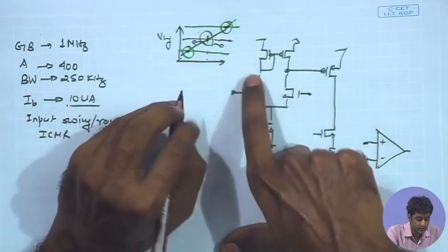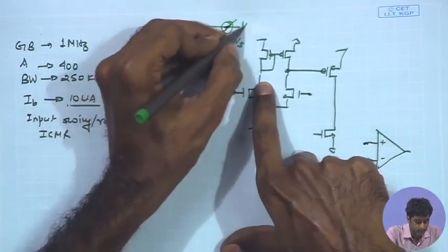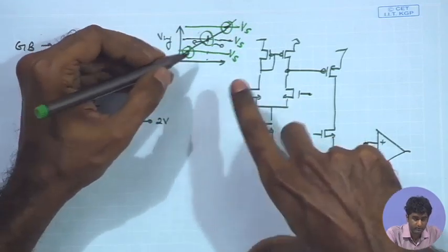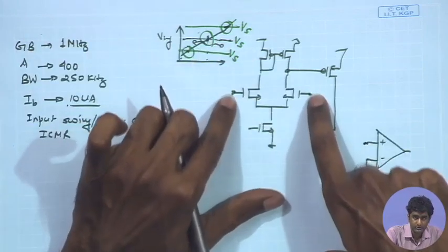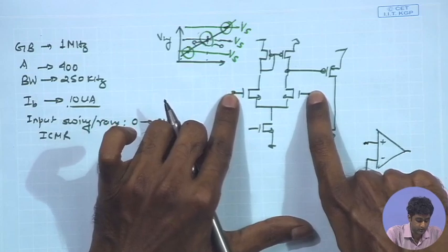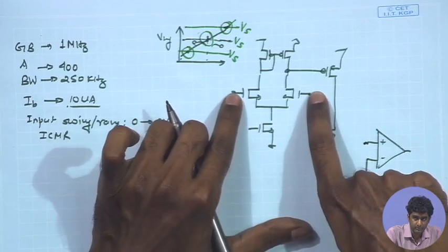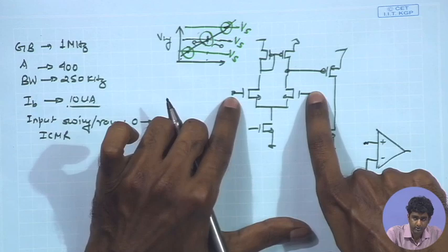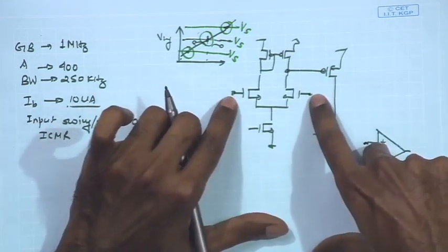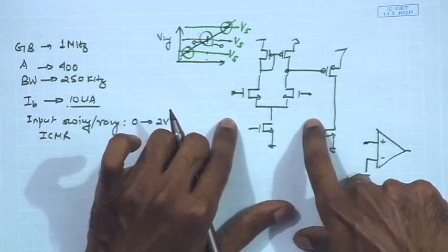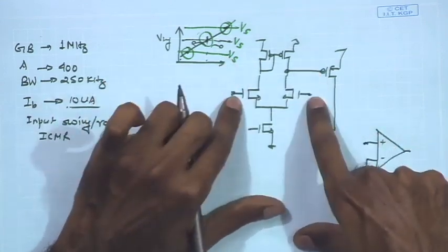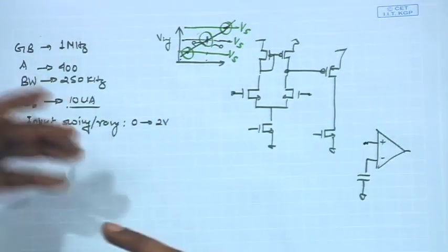The sampled signal Vs and the ramping Vref, whenever they are getting close together, that means both the inputs of the comparator are close together, and we are supposed to detect a small difference or change in polarity of V in 1 minus V in 2 at that particular point. And for that we must make sure that even for low input voltages as well as very high input voltages approaching VDD, it should be working, and that is the definition of input common mode range, right.